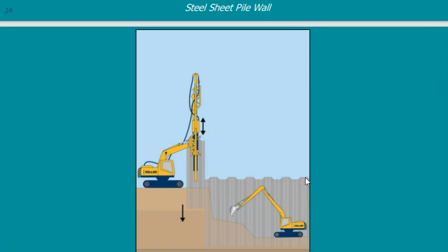Yani it started with this one, then this one, this, and now it is pushing the last one, and it will continue pushing them all together. Once I finish, I bring this machine to excavate till I reach the level I need. Here was the ground level, and I want to reach this level. So I managed by putting this sheet pile wall to excavate inside without any problem.